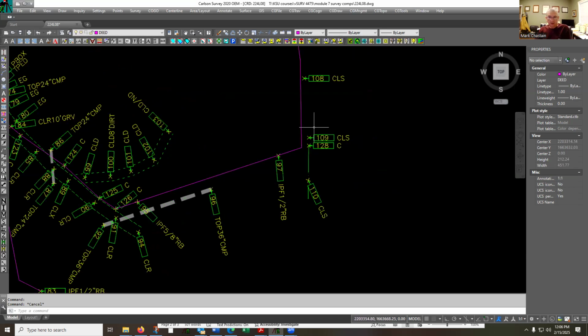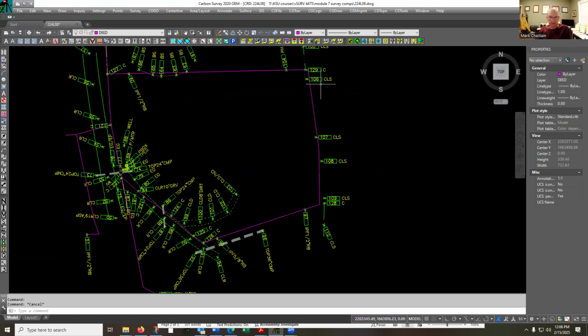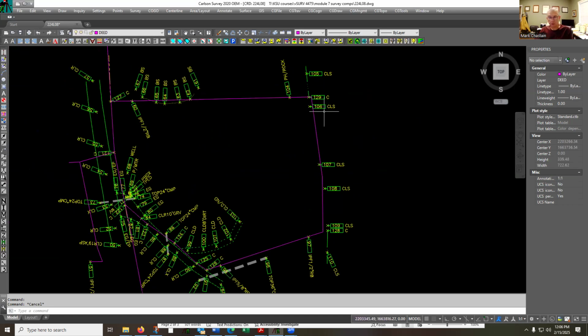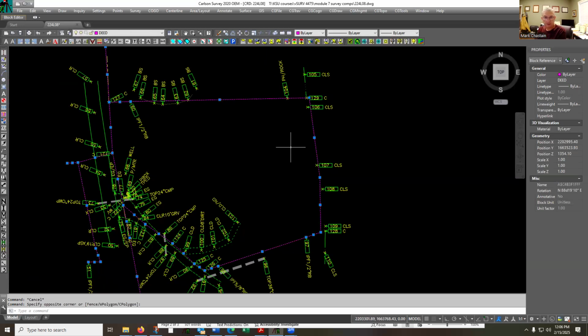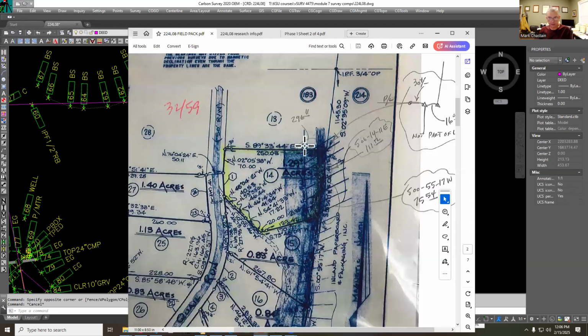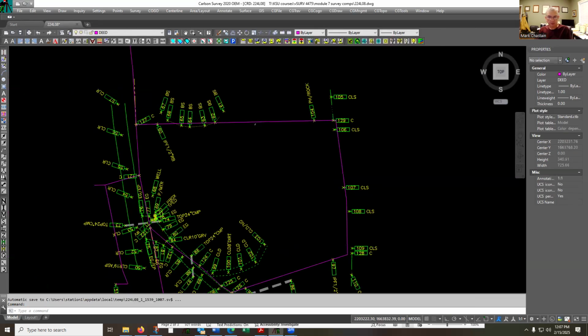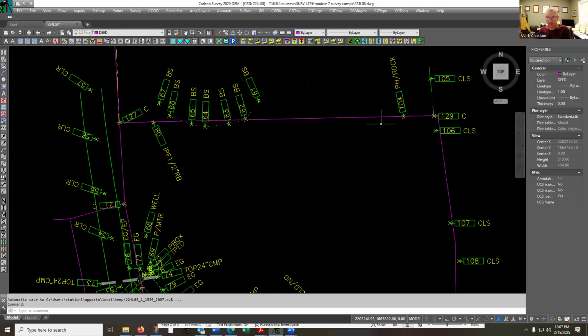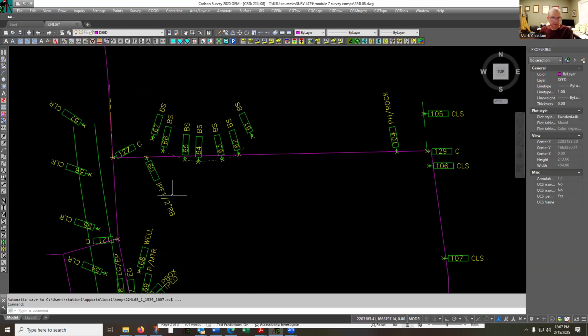So we located the creek. The creek is a riparian boundary. It's about a 20-foot wide trout stream. So where we locate the stream today is where the boundary is. That's not where these calc points or this record geometry was back in the day. So this punch hole is most likely the litmus point put in right here, indicated on the record subdivision plat. So we're going to hold 60 and 104 as original monumentation.